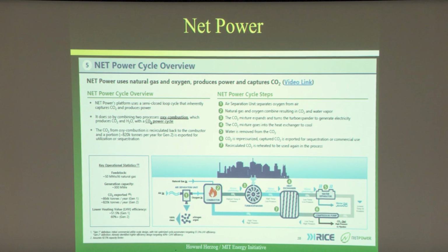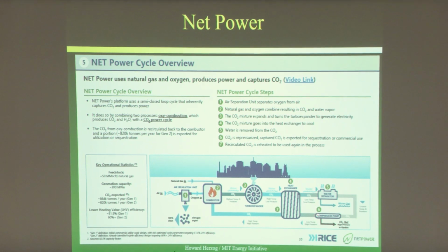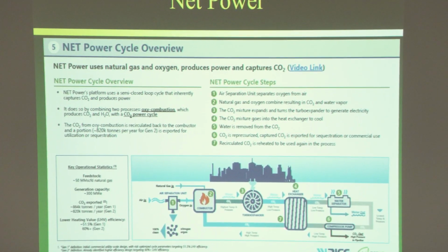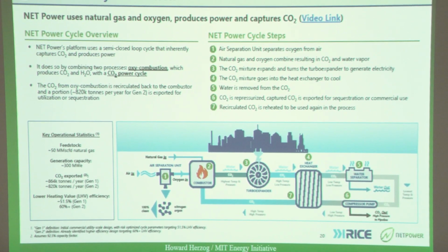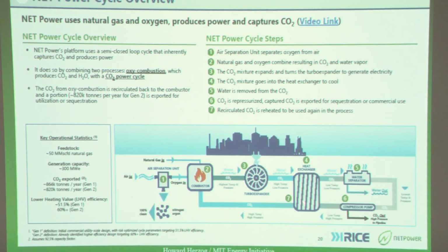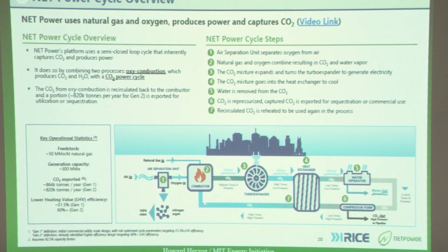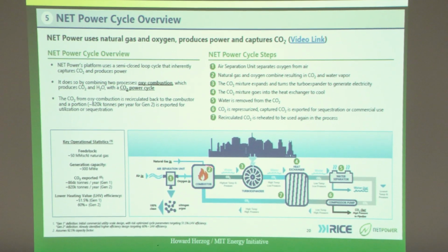Then they have heat exchange, and then water separation. They cool it down, water separation. They remove, then they compress, and they remove some CO2, and then they recycle the rest. And they recycle about 97% of the CO2. So the bulk of the mass going through the turbine is recycled. And they have the cross heat exchanger, and that goes back into the combustor. So one thing is the big recycle that they have in the plant.